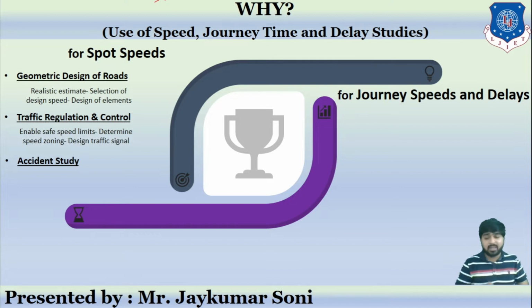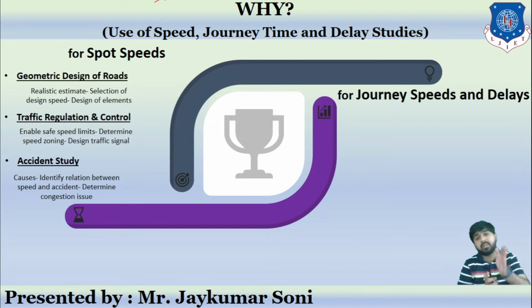Then let us take an example. If there is a road and often a number of accidents occur on that particular road, then in order to improve that situation and reduce those accidents, to conduct the accident study, we need the speed data, because it may happen that the vehicles are overspeeding. They are not driving within the prescribed limit, and those are the reasons for the accidents. So in order to conduct accident studies, to identify the causes of accidents, and the relation between speed and accident, and to determine the congestion issue, we need the speed data. For journey speed and delays, that is the second segment.